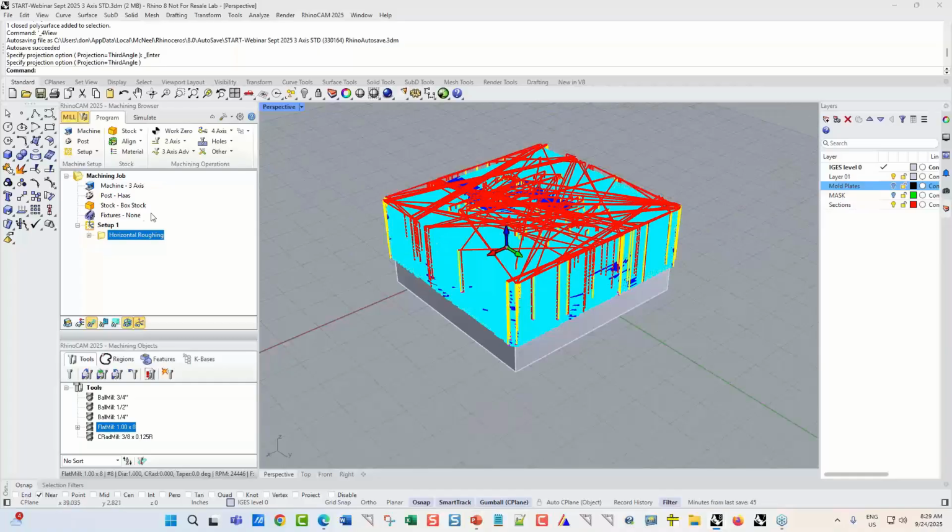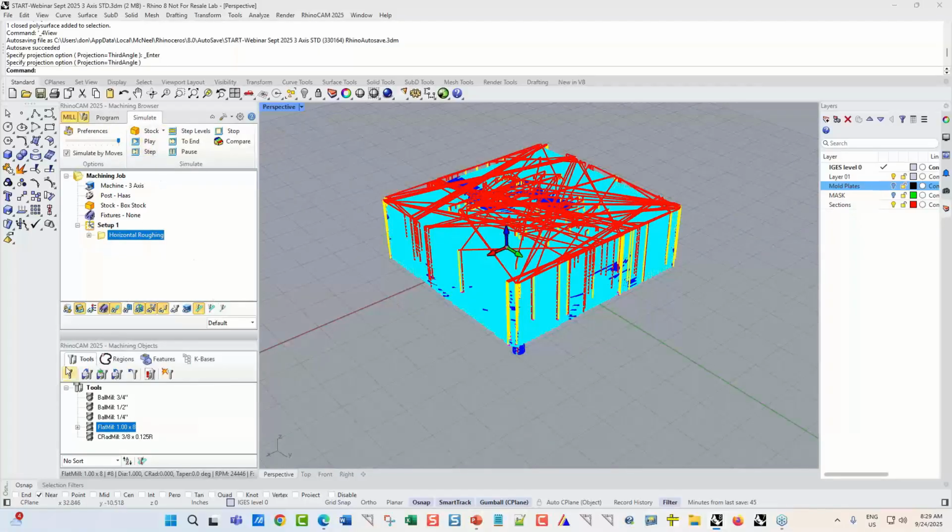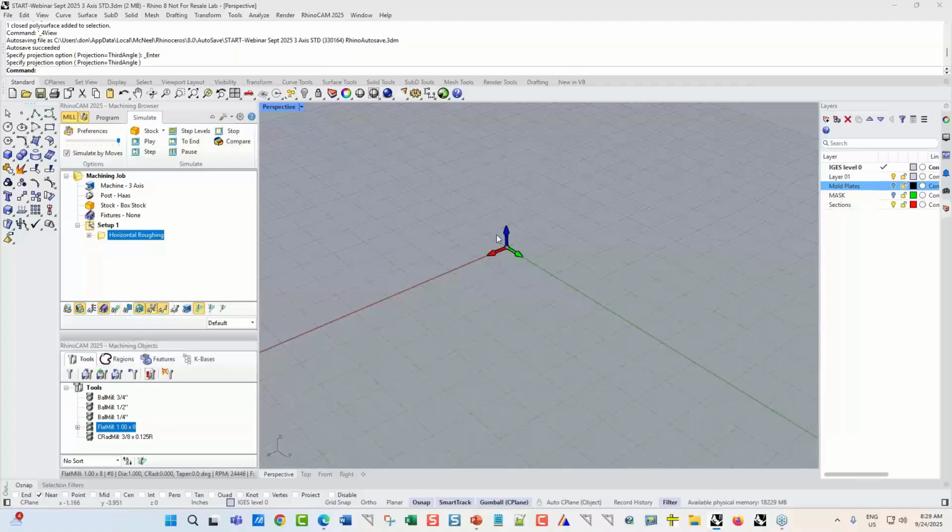Let's go up here. I'm going to turn the toolpath off for now. Okay. And let's make this as fast as I can just to get through that. If you want the colors, we set specific colors to each operation. If you want to see those colors during simulation, you need to set this to MOP. MOP stands for machining operation. Okay, so now we're going to,